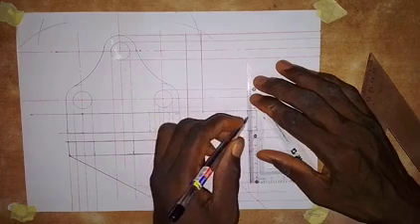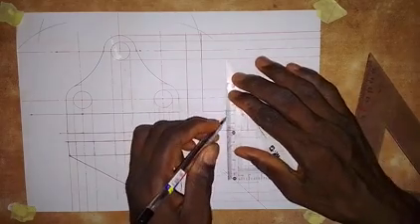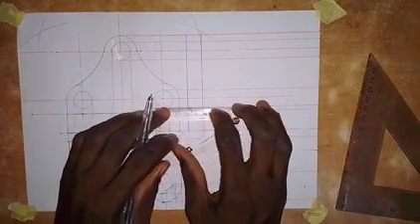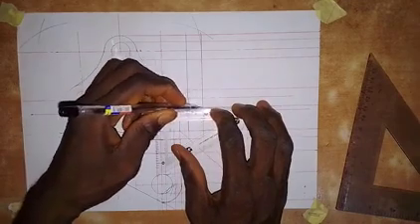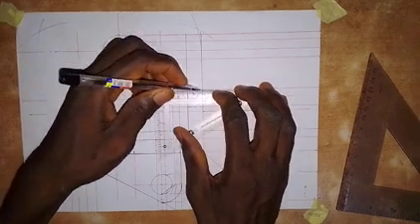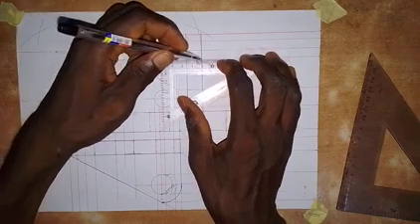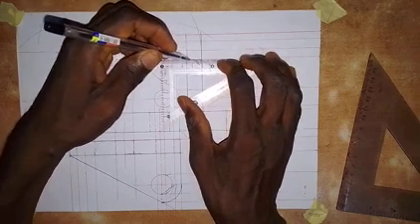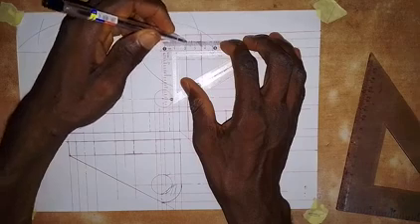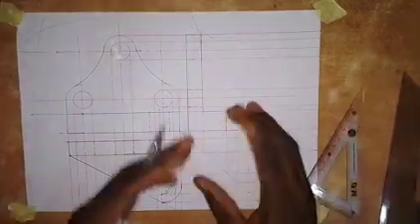Within this part, we make it a short dashes line, and we also make this one a short dashes line like this. Okay, so for this hole that we have here, this is where we have it. We are going to make it a short dashes line within this part, and then we also have the same thing here. Then up here we also have the same thing. Then we also have this, and we make this line a thick line from here to here. So this gives us the end elevation.